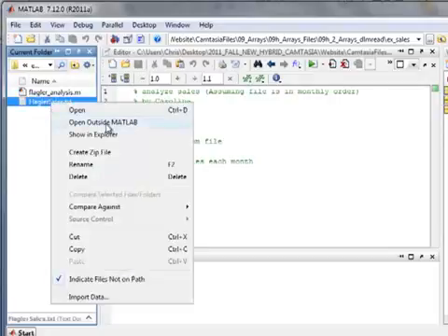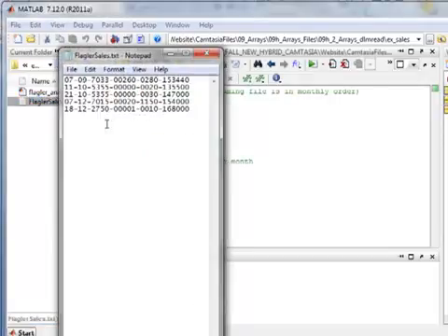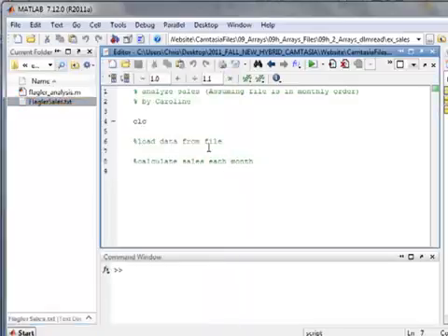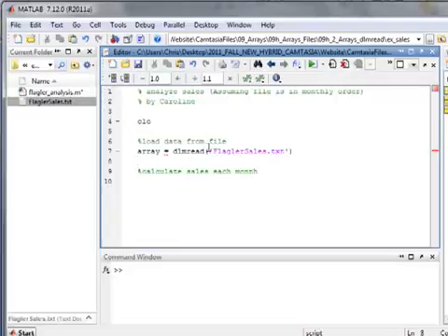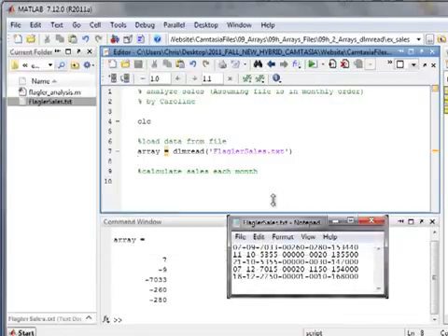Again, I can check quickly that it didn't get messed up by email or transfer, and the delimiter here is dashes. If I proceed the same way as with my airfoil, dlmread, the name of the file, remember that it needs to be a string, and run it, I notice something very strange.